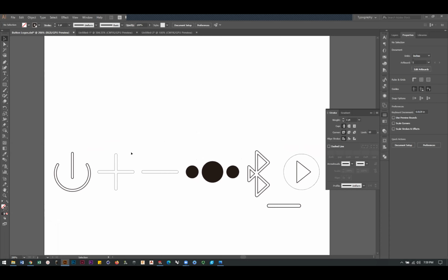Yeah, there's issues in the transfer from an AI file into a DXF. It's not a rasterization or something like that, but there's a small, microscopic adjustment between file types, and sometimes you can get some oddities that way, where the DXF file will accentuate any non-perfectly drawn line work in Illustrator. So you just need to be extra careful when you're making graphics.